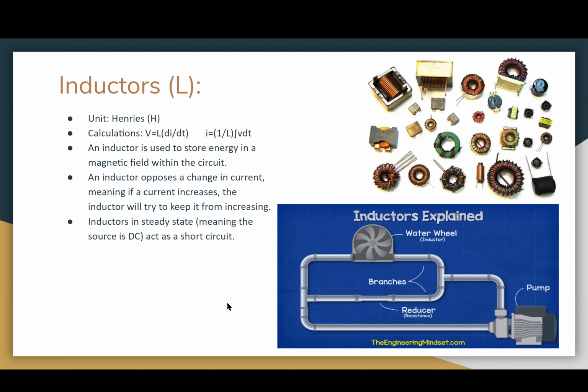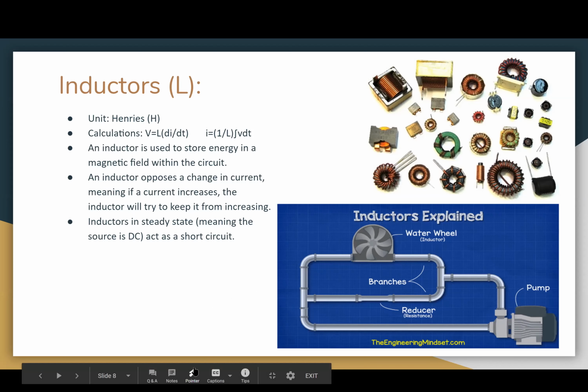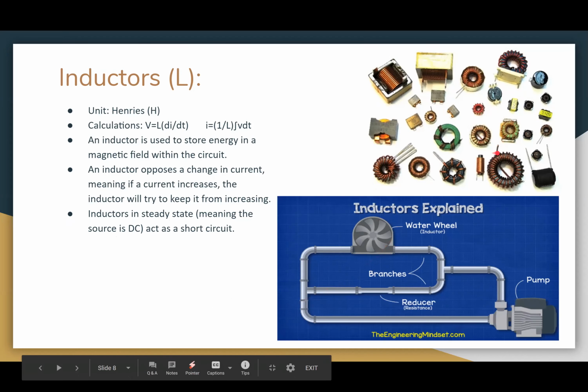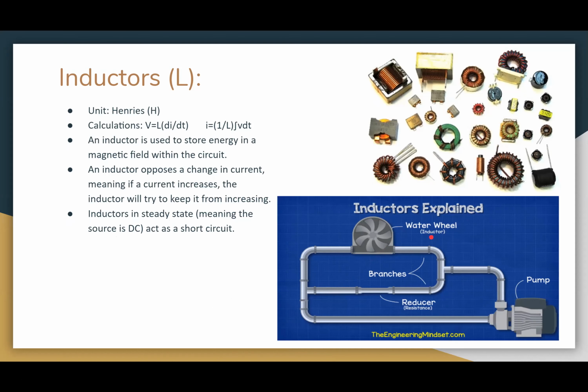And with the inductor, if you look at the picture over here on the slide, they're all coils. Coils are just wires, coiled up. So just imagine that with a DC source connected, that coil just gets stretched out and turns into a regular wire, with no resistors, anything. So it's just going to be a short circuit, and the current's just going to fly through there. Yeah.